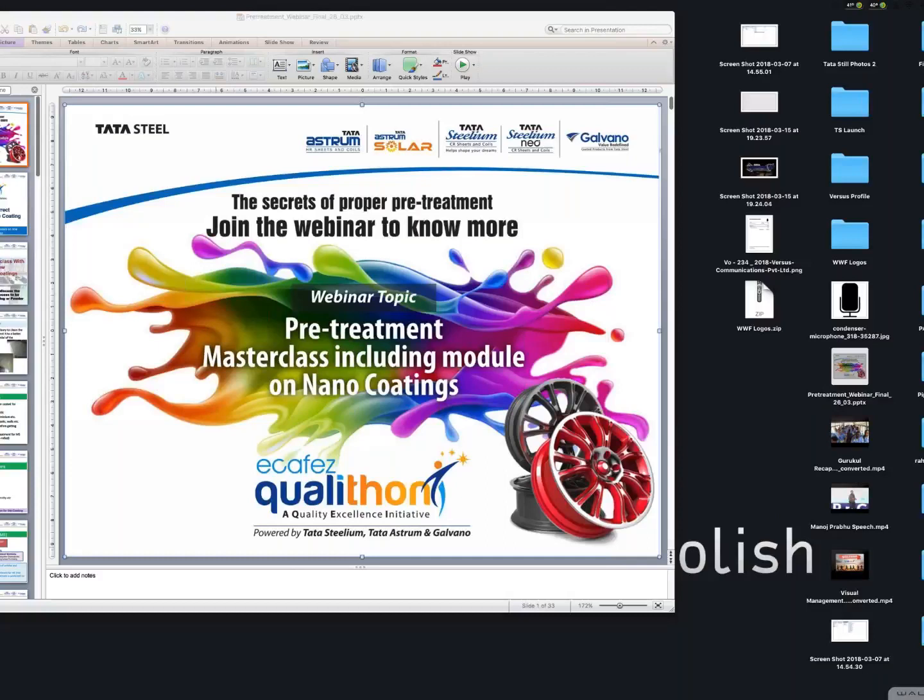Now again here, if you are using a phosphoric based de-rusting, the risk is lesser. But if you are using HCl, HNO3 or H2SO4 based, the risk is more. So please, please, please don't do that.